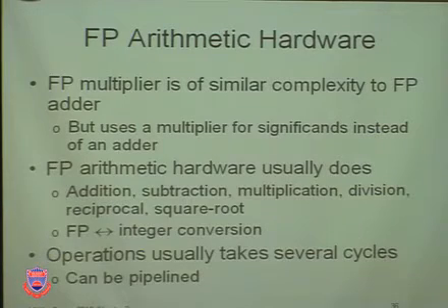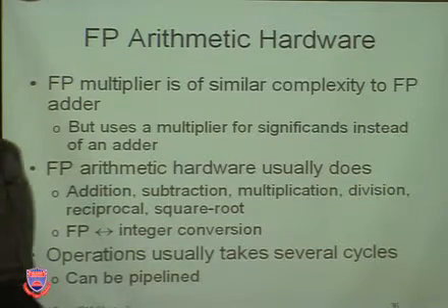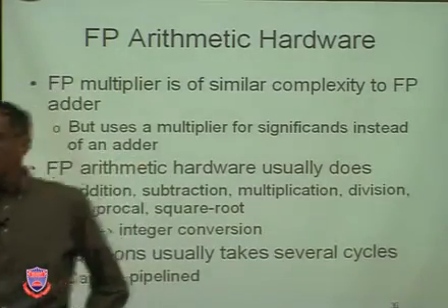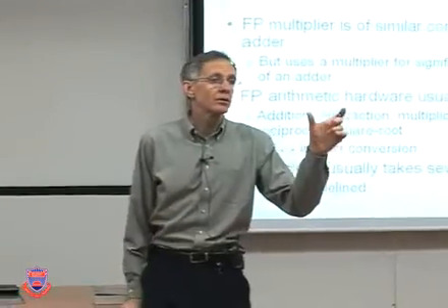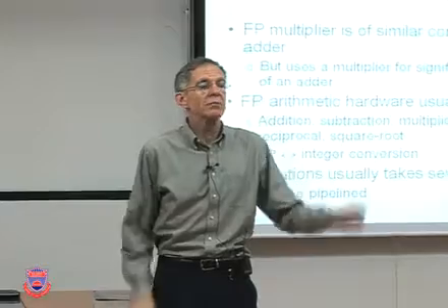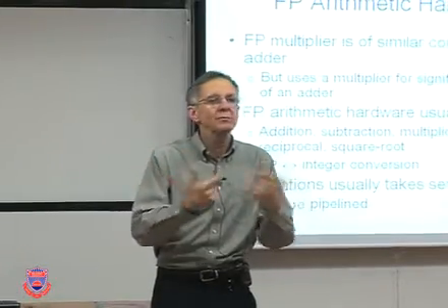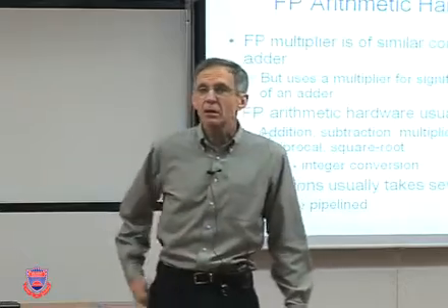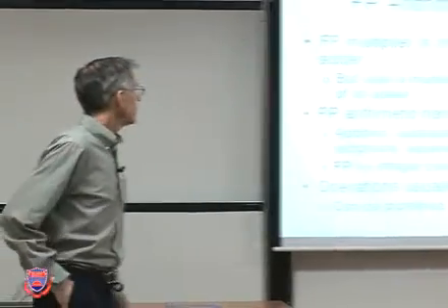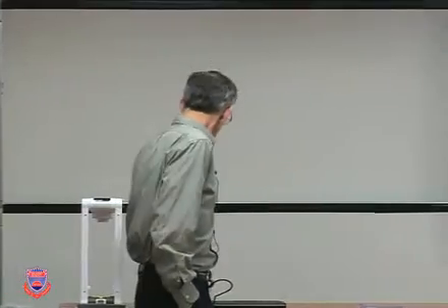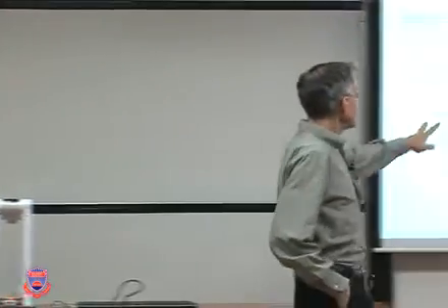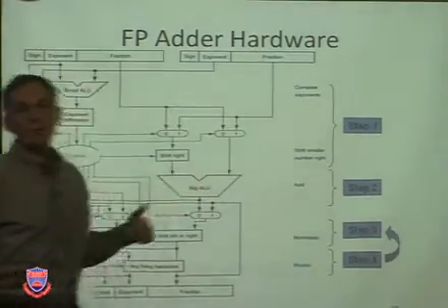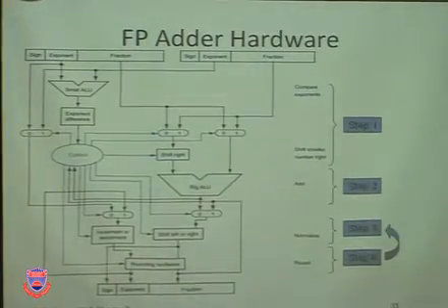Let's move now to floating point multiplication. I think we all recognize, don't you, in multiplication, we multiply the two fractional parts and we add the exponents. So there's no need for the exponents to be the same. We don't have to compare them, find out which one is bigger. So there'll be similarities. We're going to use a multiplier now for the significands and not an adder. If you step back one, here we're actually adding the significands. Now we're going to need to multiply the significands. And so